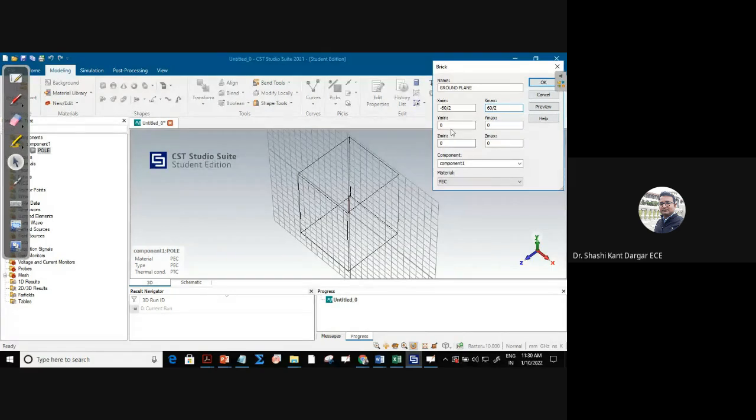And the Y minimum, the Y thickness should be 0.02 only, from 0 to 0.02 thickness. So if I do it upside, then the brick which is going to be created will go in the Y direction upside. Yes, 0.02. If I do like this, see the difference between this, right? Let me show again here.